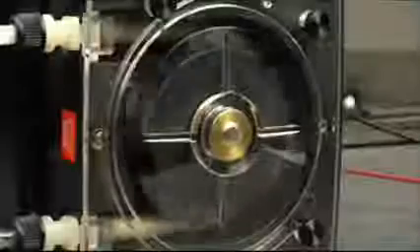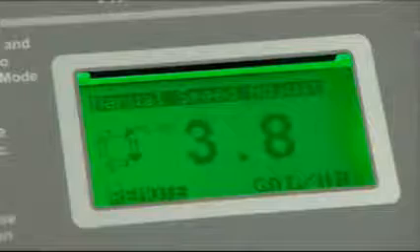Use the front panel Select Run Mode button to select the operating mode of choice. Press the Start button. Note that the display indicates Standby. Depending on the contact input setting, the pump will either start or stop when the circuit is closed.